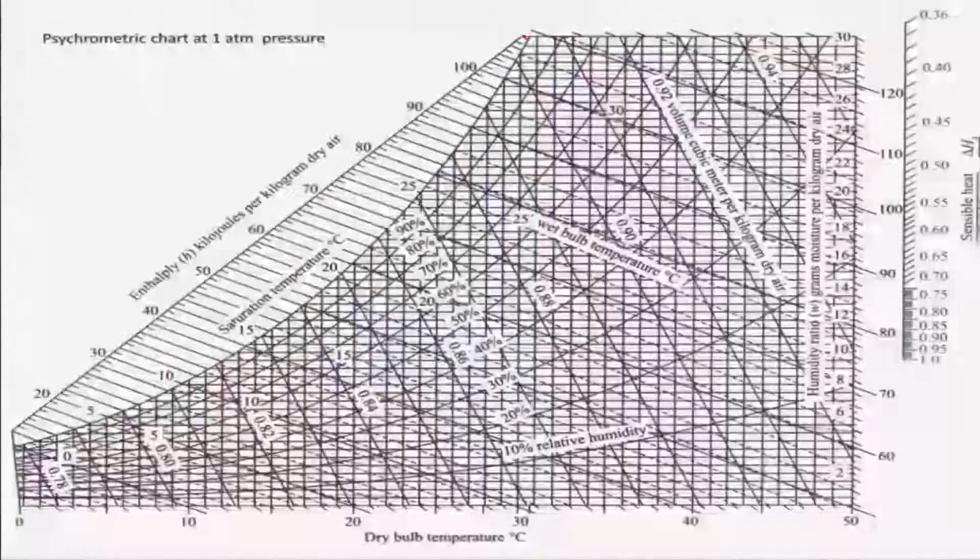If you want a different pressure, it will be different. For example, when you go to a higher altitude, the pressure will be lower, and then you will have slightly different values. Now, if you recall, we had taken a dry bulb temperature, and we also looked at the wet bulb temperature as 30 degrees Celsius. We solved this problem by calculating and considering it as an adiabatic saturator. We can do that very easily here, because we did a lot of calculation, but here it is easy.